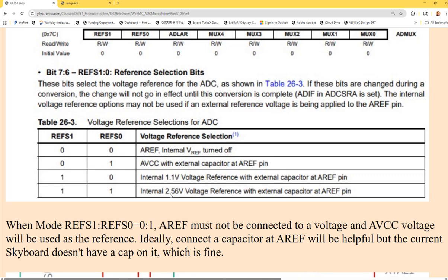For example, there's a sensor you know. It could be an analog temperature sensor, or an analog humidity sensor, outputting something like 10 microvolts, and you only have Arduino's ADC to use. What can you do? The smallest voltage you can detect here is about 1 millivolt, but it's the 10 microvolt change that you have to resolve.